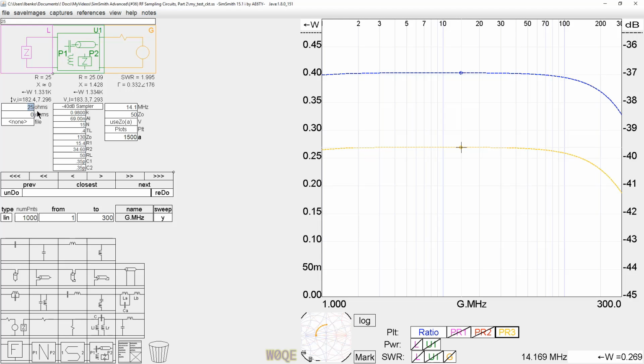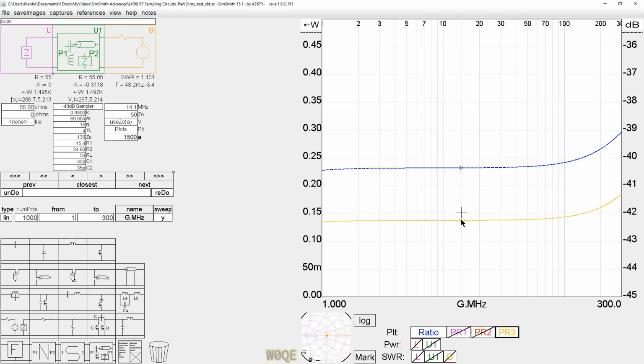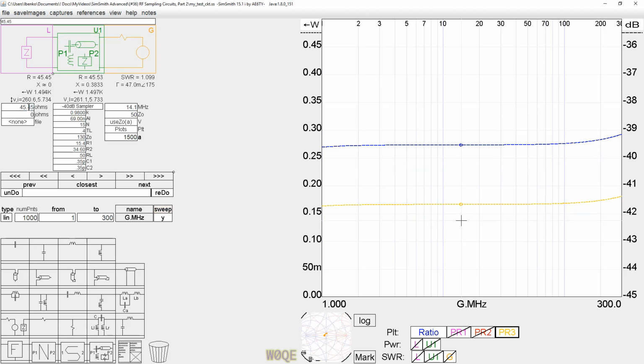If we look at this and go to 50 ohms, we see that the value here at 50 ohms is 1,500 watts. When you multiply that times 10,000, I'm going to go up to a 1.1 to 1 SWR, and it went to 1,380 watts, down again to 1.1 to 1 SWR, 1,660. That range is not huge, so if I keep the SWR under 1.1 to 1, this is a very useful solution and considerably simpler to build than an SWR bridge that can cover this frequency range.